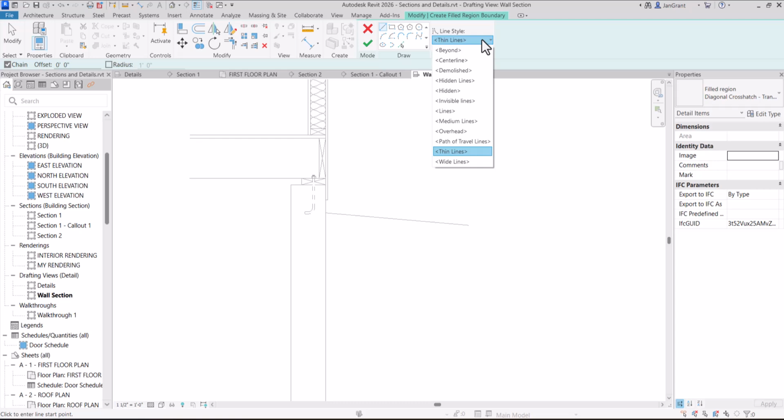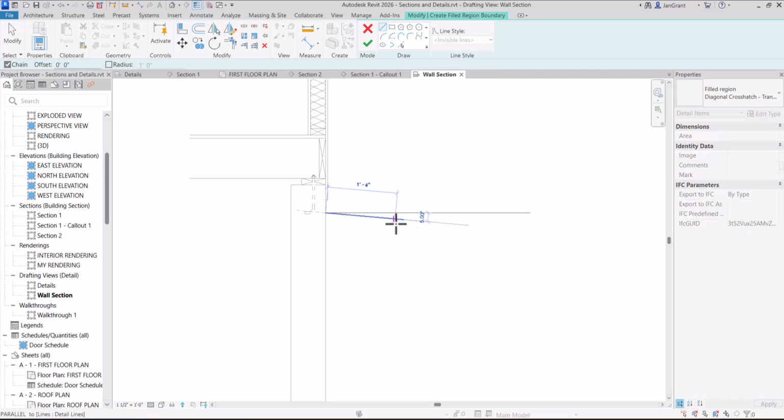So I think at this point it might be better while we're drawing it to click on invisible lines so that we don't have like the boundary showing. And now I can start to click here of where I want this earth to come across and up here and kind of have this fill of earth to show that that's the ground.